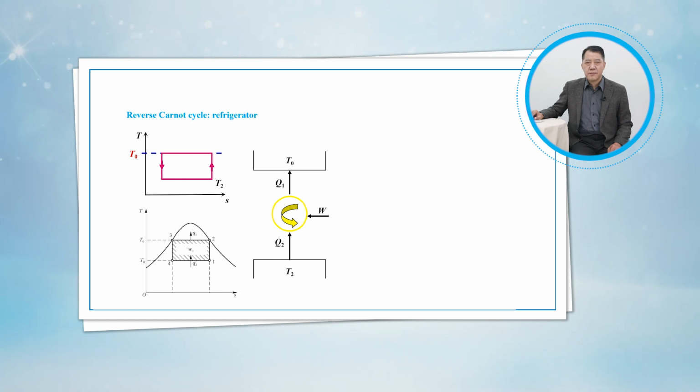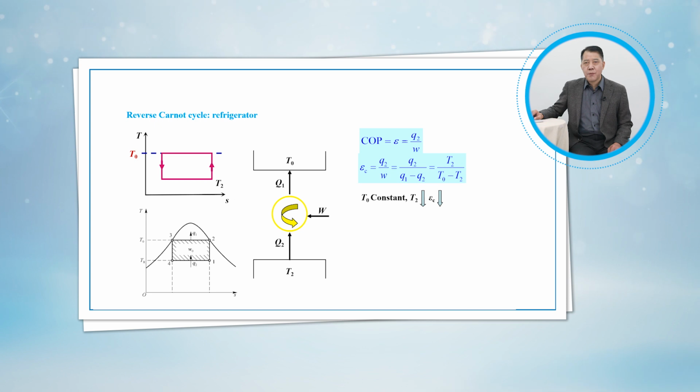The refrigerant changes from a saturated vapor state to a saturated liquid state in the condenser during process state 2 to state 3. The coefficient of performance of Carnot refrigerators is expressed by definition and in terms of temperatures as: Notice that COP increases as the difference between the two temperatures decreases, that is, as TL rises or TH falls. Generally, TH is the environmental temperature T0 for refrigerators.